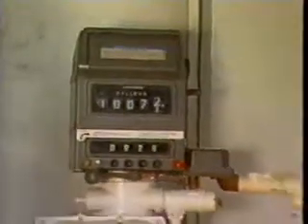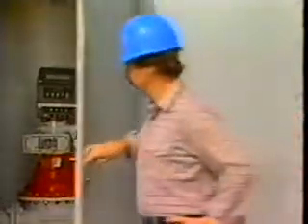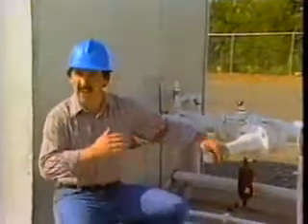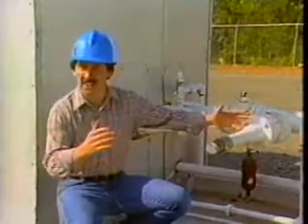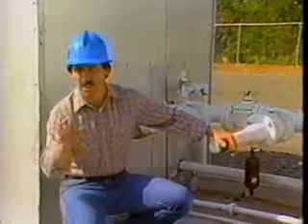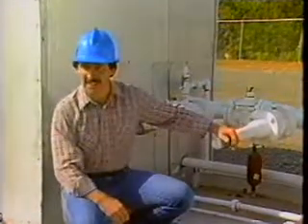Liquid meter proving is the physical testing of the performance of a meter that is in service, measuring the flow or volume of a stream. The meter proof is performed by placing a meter in series with a meter prover, which has a known base volume for standard conditions. The prover is installed so that during a test run, all product measured by the prover is also measured by the meter.